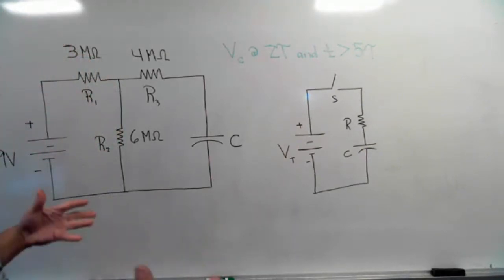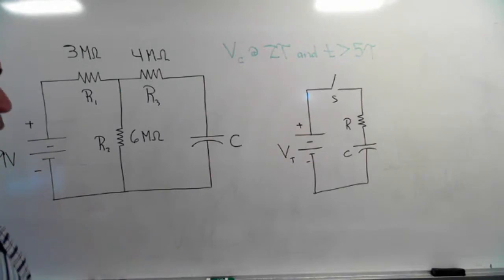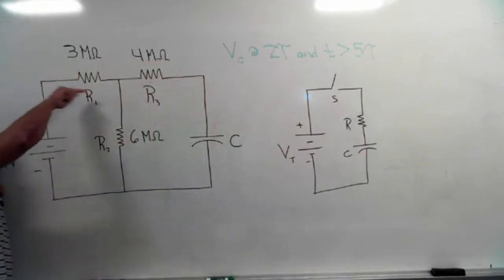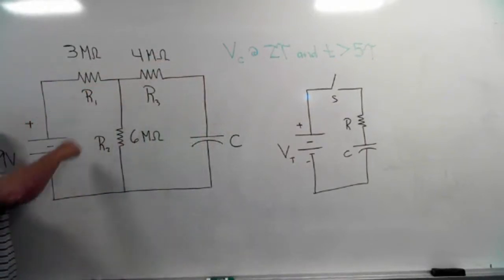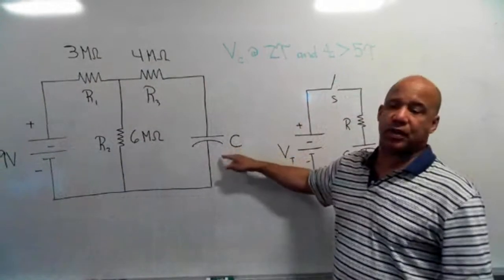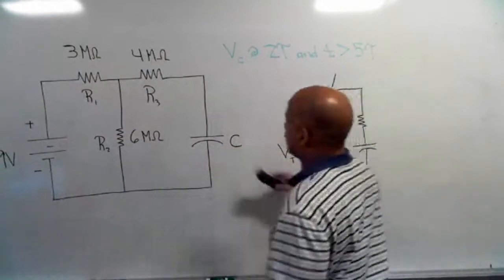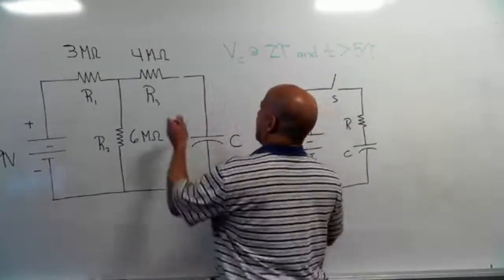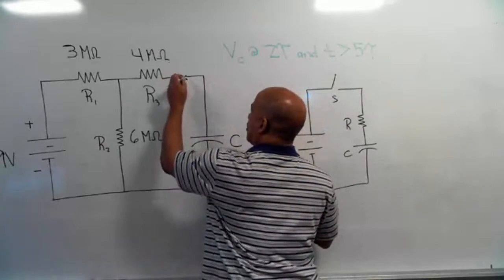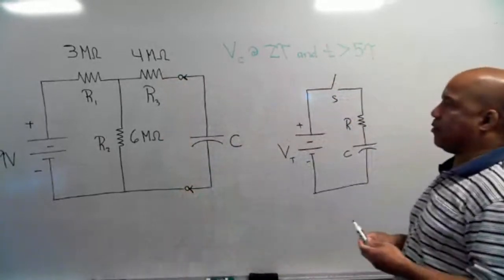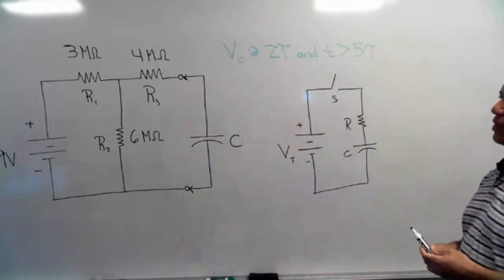In putting the resistors together like you suggested, you don't want to know what the total resistance is looking this way in the circuit. You want to know what total resistance the capacitor sees. So it might help if I put these little terminals on there. Hopefully that made you think of when we had to do Thevenin's theorem.